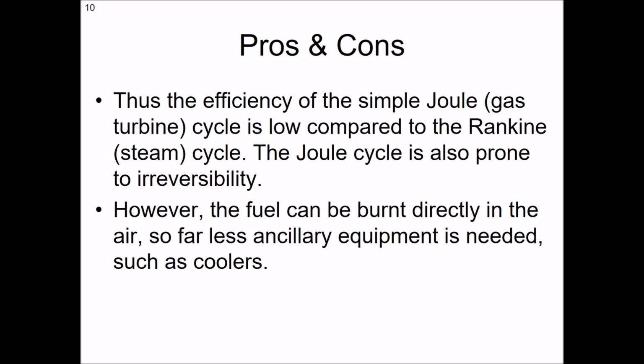We want to throw all that energy out at high speed, but that's really hot gases that are going to waste. What we'd like to do from a thermodynamic textbook point of view is throw the energy out of that engine at a very low speed, at a very low relative temperature, and harness as much energy from the gas as possible. But that's not going to give you very good thrust.